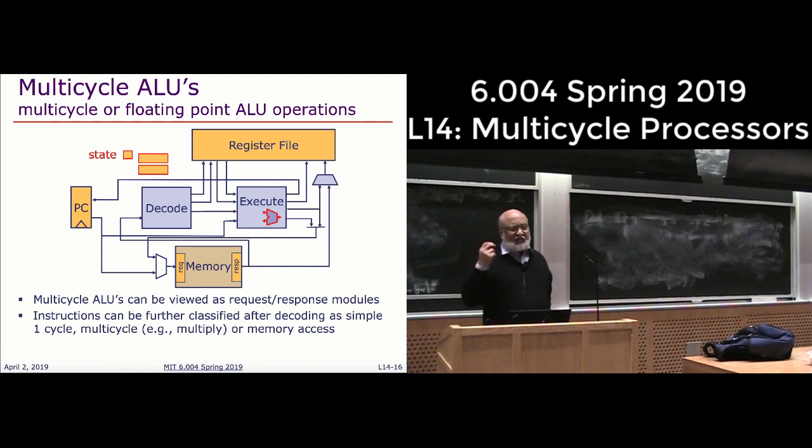So now the question I'm asking you is, can you actually integrate that multiplier into your design? Now suppose, this is not true, but suppose the multiplier takes 10 cycles. Should every instruction take 10 plus cycles? See, that'll be pretty dumb. We are smart designers, so we should spend those 10 cycles only if you happen to execute a multi-cycle operation, only if you happen to execute a multiply instruction.